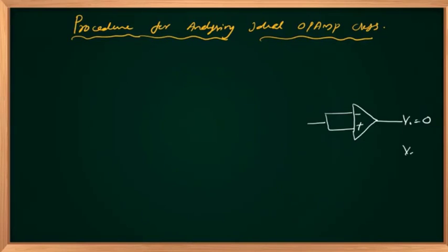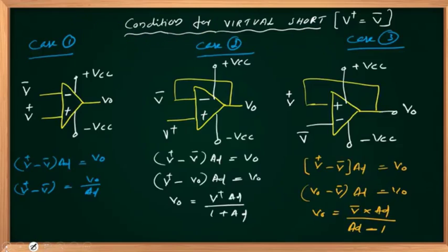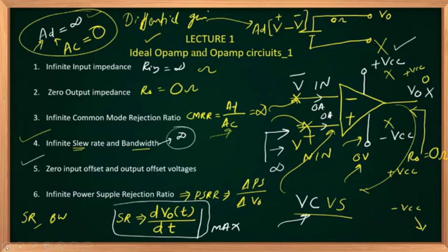Sometimes you may not be getting a 0, V out not equal to 0, right? So that voltage is called output offset voltage. The voltage present at the output side of an op amp when its input terminals are shorted together. Ideally, I'm expecting a 0. So ideally, output offset voltage should be 0.